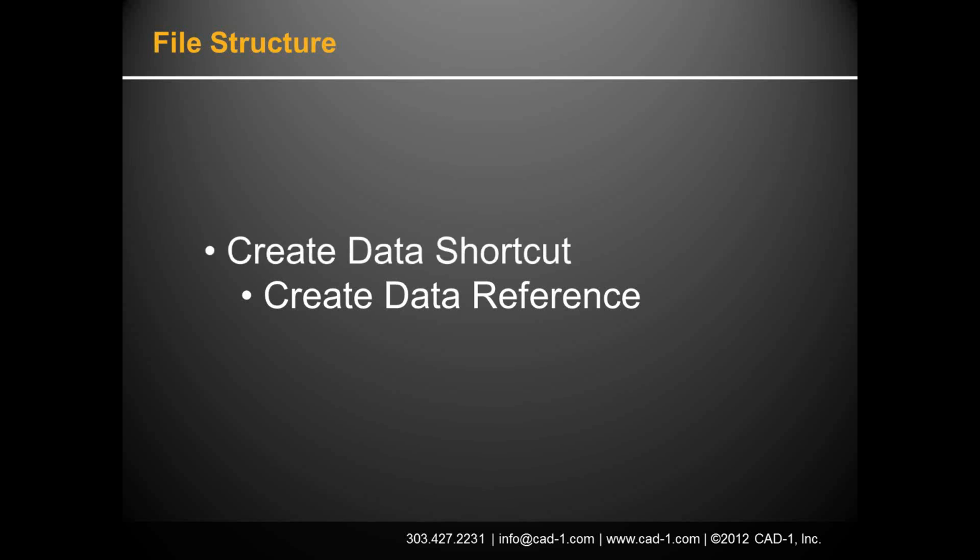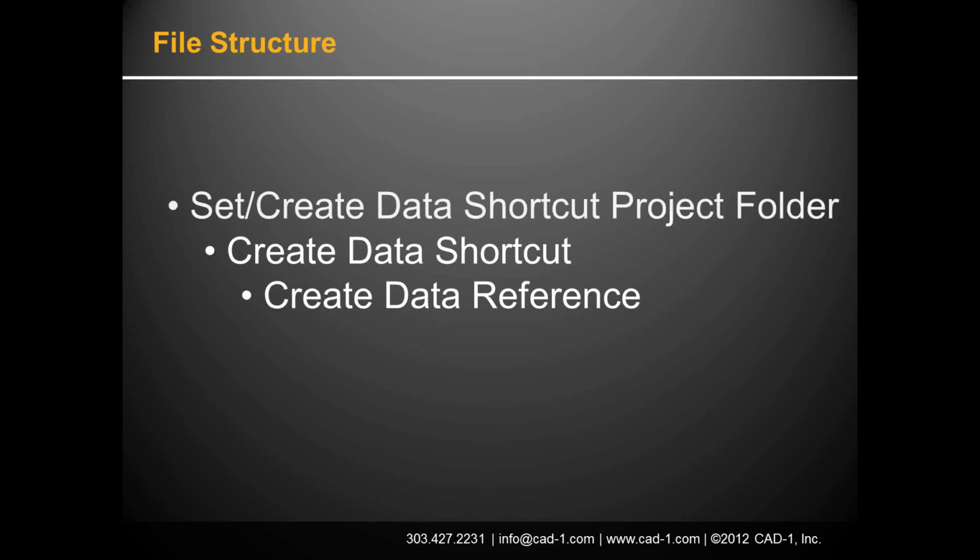Now, before I can create the data shortcuts, I need to tell Civil 3D where on my network I want to store these little shortcut files. Because again, it is an object on my drawing somewhere. And so I need to set or create the data shortcut project folder.